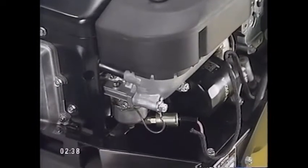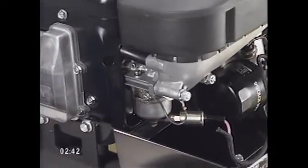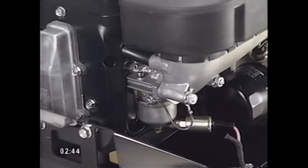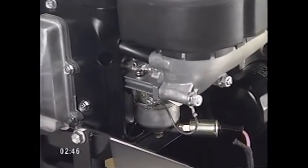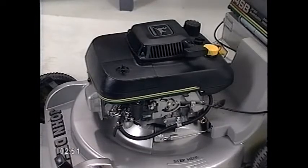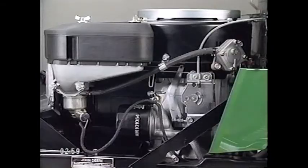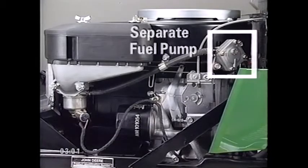After leaving the filter assembly, the clean air then enters the carburetor. We'll have more on our carburetors in a few moments. First, however, let's look at the fuel system. There are two basic ways to move the fuel from the tank to the carburetor. If the fuel tank is positioned higher than the carburetor, gravity feed is used. But if the tank is lower than the carburetor, a fuel pump is required. In some instances, a fuel pump and gravity are both used in combination.